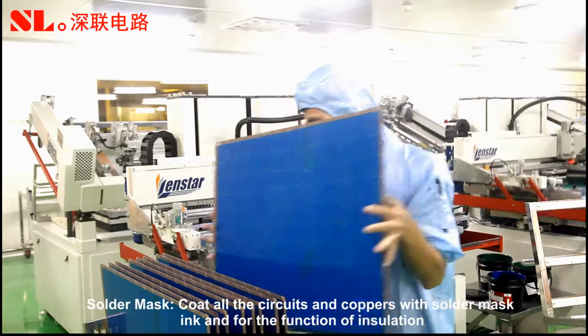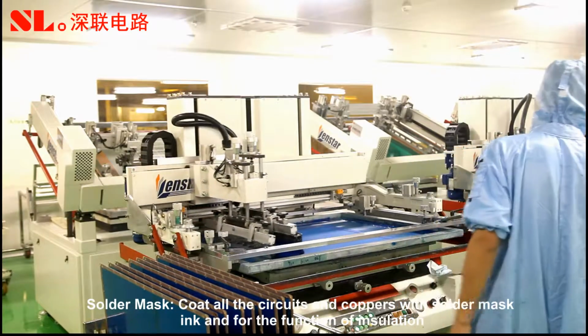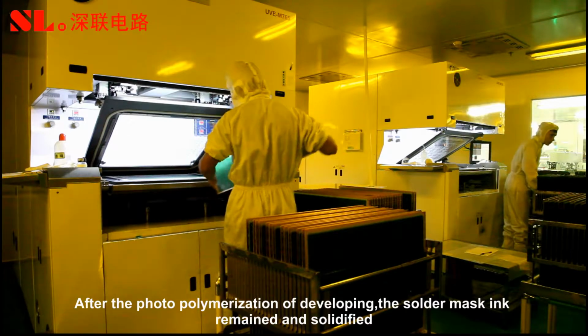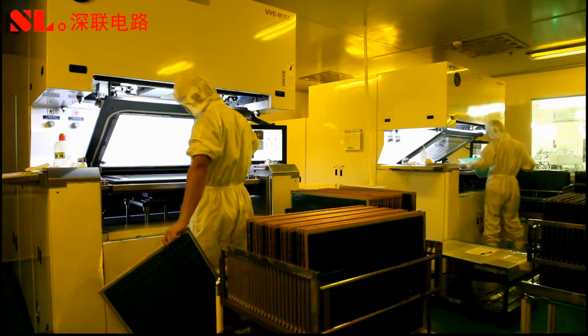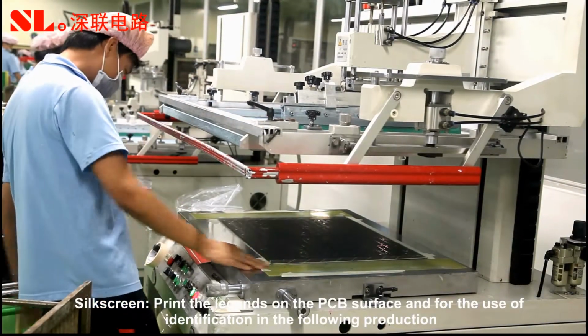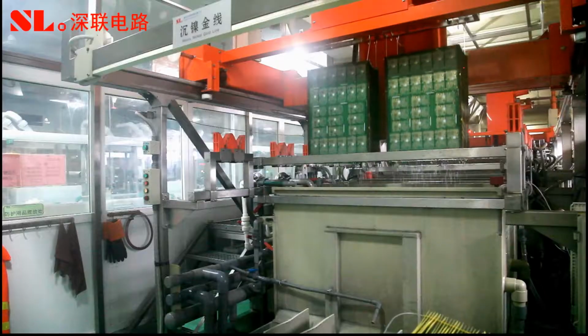Solder mask. Coat all the circuits and coppers with solder mask ink and for the function of insulation. After the photopolymerization of developing, the solder mask ink remained and solidified. Silk screen. Print the legends on the PCB surface and for the use of identification in the following production.